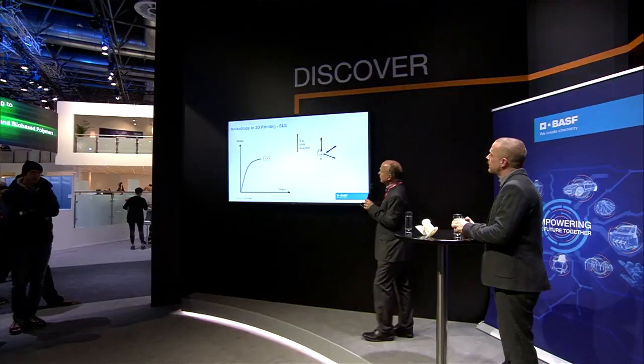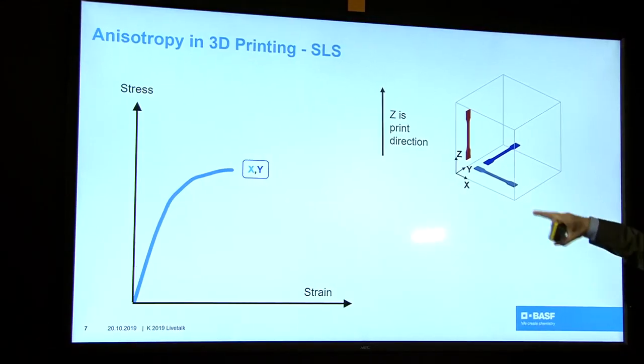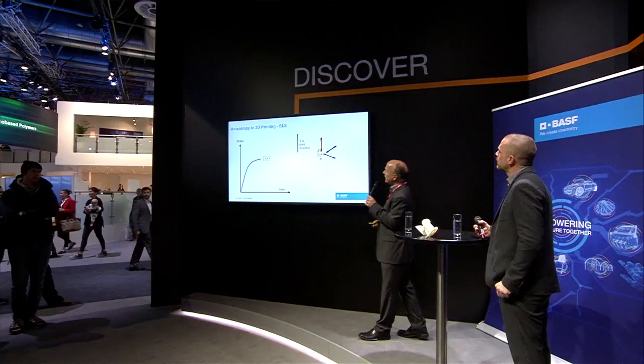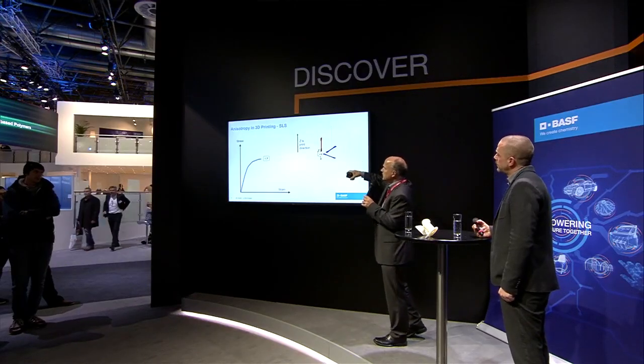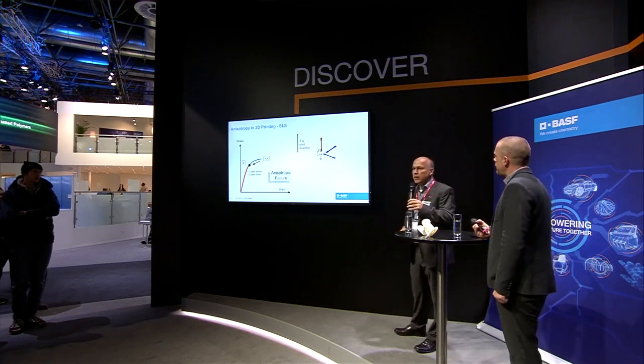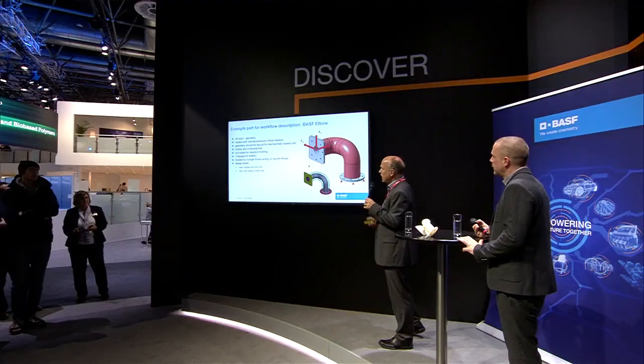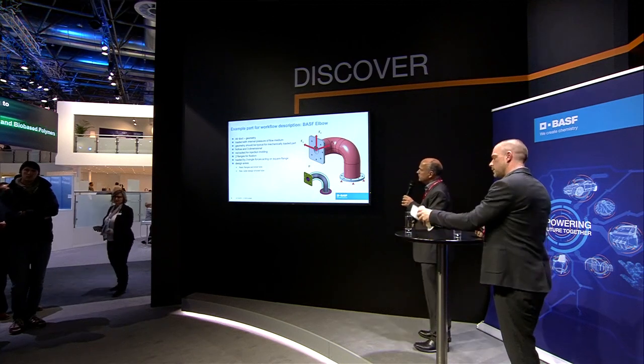When it comes to description of the material, it's different than in injection molding. In 3D printing, for example, you have this layered scheme, additive. You basically build in slices, and the Z direction certainly is something weak. So the engineer says we have an anisotropic failure behavior, and this means we have to define that. And our tool that we have here, Ultrasim, does the job also in 3D printing, so we can use it directly for that.